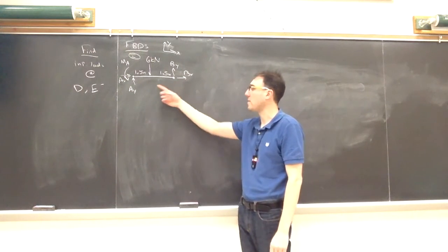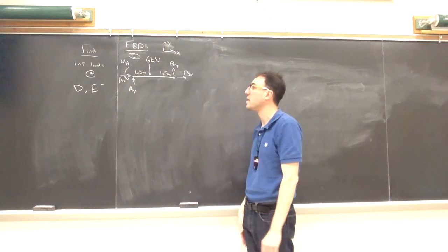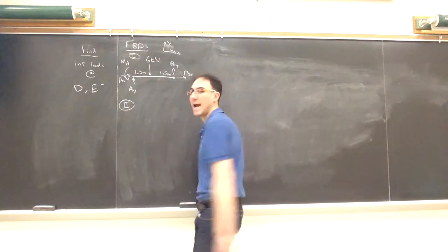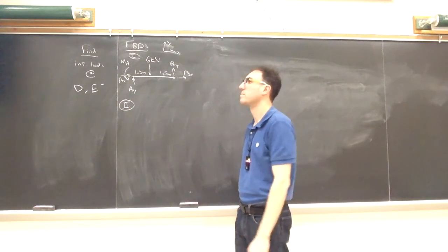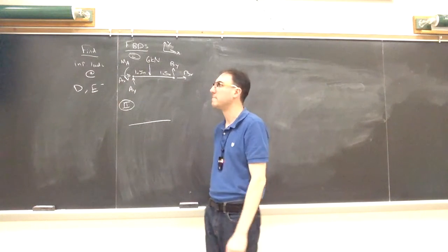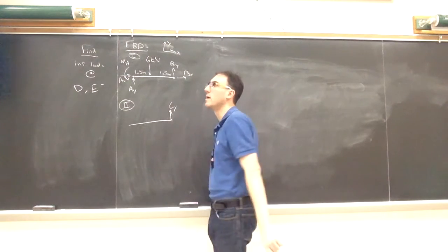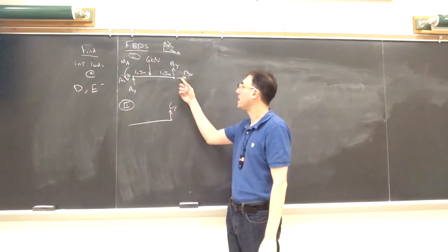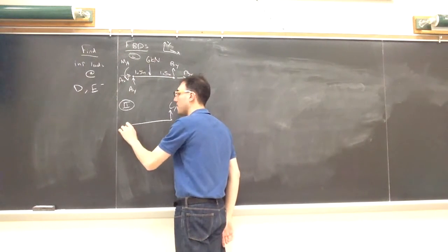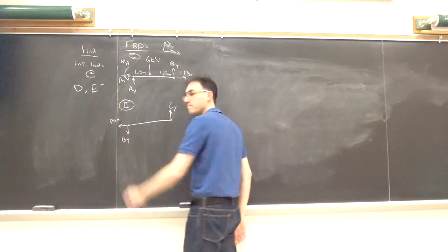If I look at this picture, I have 5 unknowns here. So I'm actually going to hold back on writing equations and see if the second picture is going to be an easier place, mathematically at least, to start. Separating this out then, I can draw from B to C. I have that roller at C. And that internal pin at B, I've already assigned directions in my first picture, so I have to have equal and opposite directions in this one.